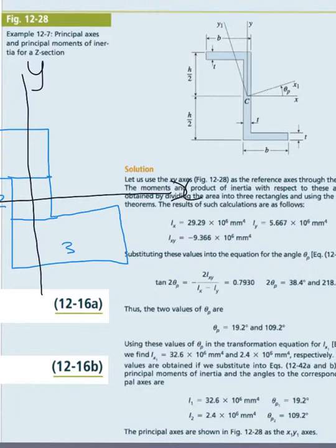And basically when they say IXC, the moment of inertia for an area that is offset, if we are looking at this rectangle here, it means that if we want to calculate its local moment of inertia, we will have to look at its local coordinate system. I'm just going to do it in dotted line.